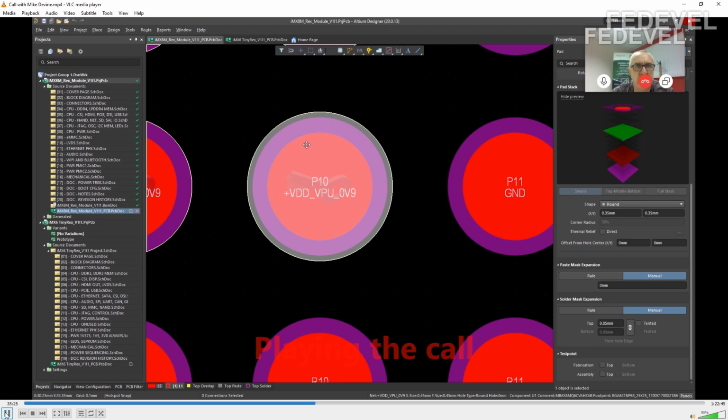200 micron through vias across the whole board. Now, but only in certain areas do they need to be copper filled. If it's easy for you, you could set those vias at 201 microns. Okay. Actually that separates it out on your drill program.